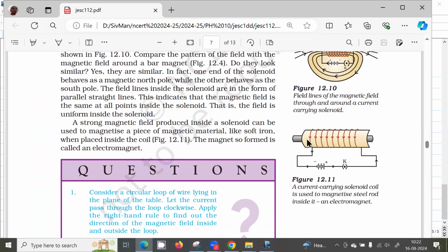That's actually creating a path for the magnetic field lines to flow easily. Like current in a particular channel, that's the conductor, right? Similarly, if you have a magnetic field, I can create a region where the field lines can pass easily. So that is the soft iron core. That's called magnetic permeability. For soft iron, the magnetic permeability is high, which means it allows the magnetic field to pass through it easily.